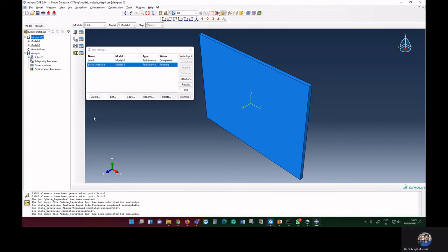You have to wait. Okay, so in between, you just do one thing, you note down your result with the C3D8R element with 4 layer. Now we'll get the C3D20R element with 4 layer. Okay, so we'll see how much the result is changing. Once we get this result, the next job will be to check our orientation from theta 0 degree to 90 degree, and we need to check whether our result is changing or not.